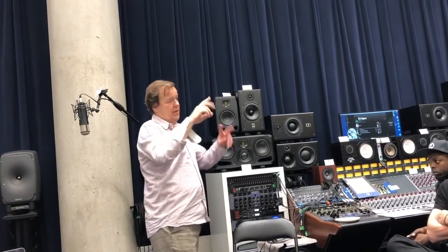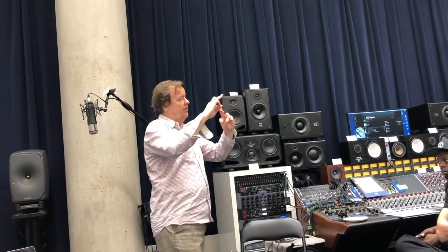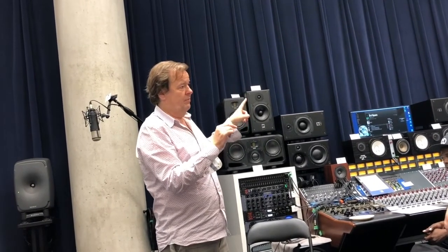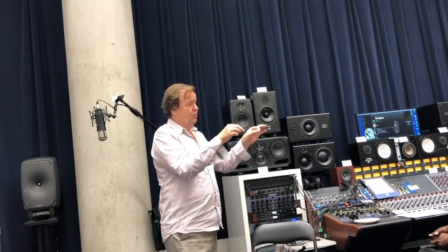And what we added, as I said, is 2 preamps, so we have a 137 dB dynamic range. But those 2 preamps can also be driven individually. That means a front of house and monitoring can each have their own gain. Then you don't have the 137 dB dynamic range, but you have two independent gain controls that two different people can manage. This is not the case in the Hapi or Horus.